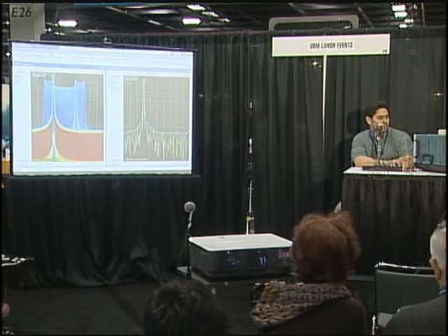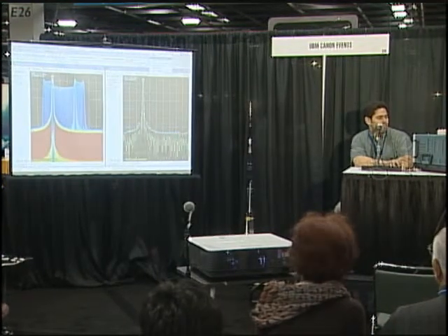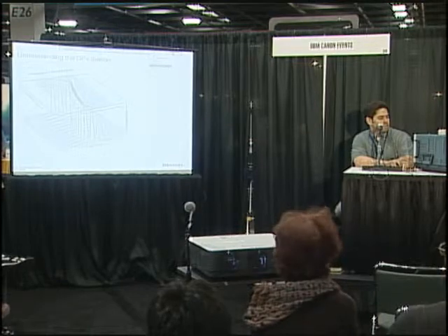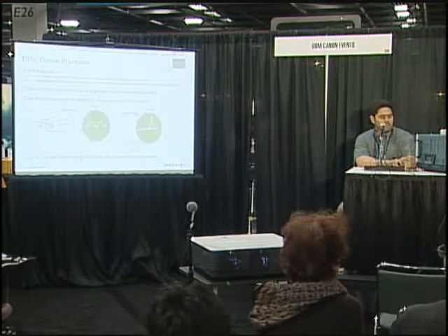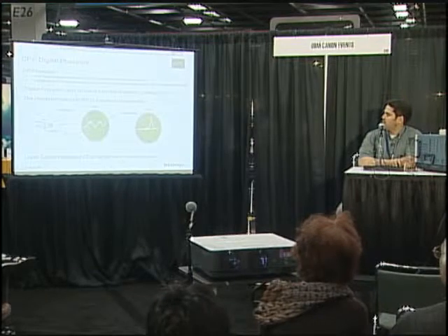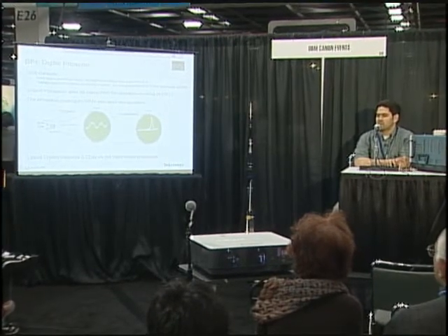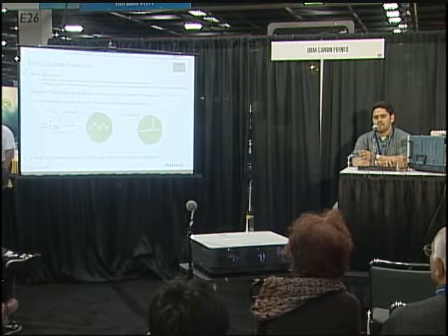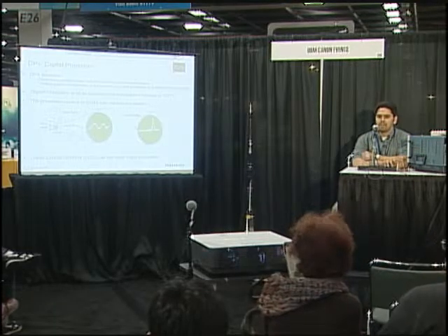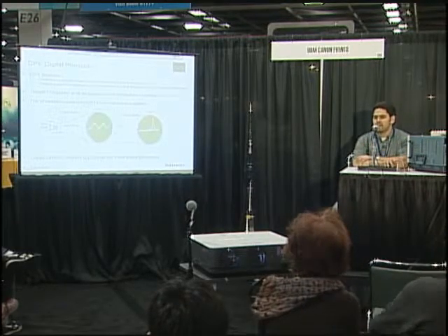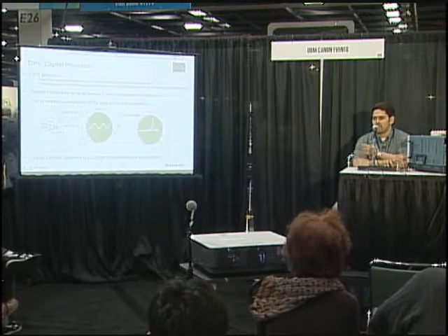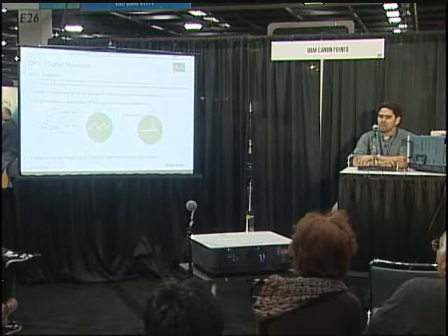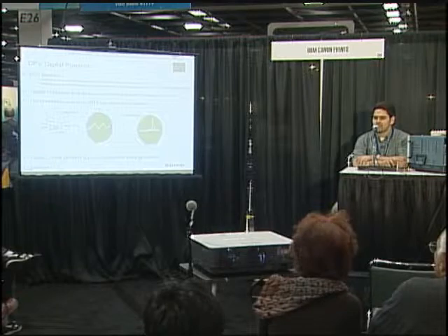So I'm going to show you a slide now to exemplify this a little bit better. DPX. So like I was saying before, it's mimicking that property of the old phosphor-coated CRTs. In those old monitors, if you saw something brighter, that meant that it was more repetitive, right? So the level of intensity on the plot will give you information about how persistent the signal was. And the next thing we're doing is very fast update rate. So we're doing actually close to 300,000 spectrum updates per second.